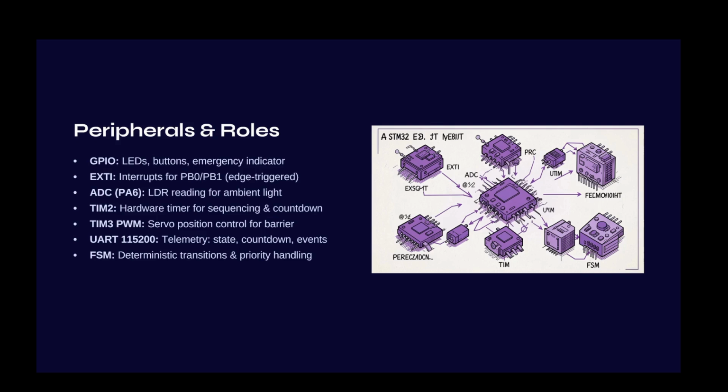ADC. The LDR sensor produces an analog voltage. The STM32 cannot process analog signals directly. Using the ADC peripheral, I learned how to convert analog sensor values into digital values. These readings are then used to detect day and night conditions.